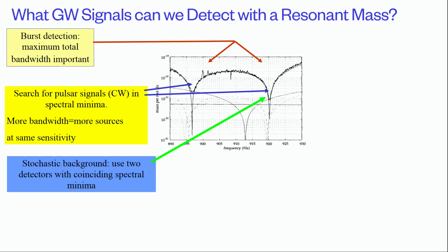The integration physics should be thought of as the signal integrating in my detector, and the noise will stay constant at this per root hertz level. It can depend on the noise. What I was saying earlier, if it was statistical noise from the spectrum analyzer, you can average down, and maybe after like 50 averages, we give you this plot. When we give you this plot, it's saying that we've done the maximum number of averages, and it's not going to go down much below this, right?